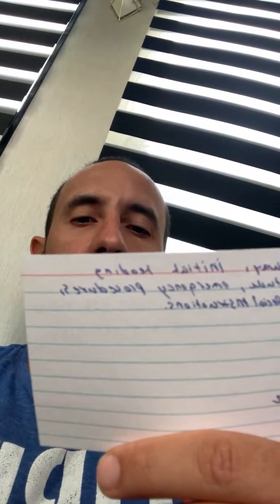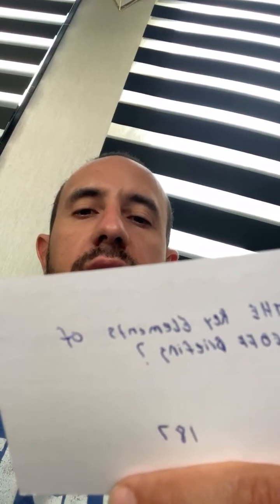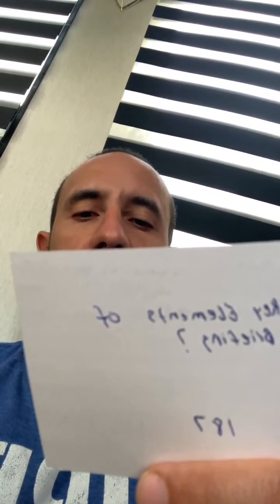What are the key elements of pre-takeoff briefings? Departure runway, initial heading, assigned altitude, emergency procedures, and any special instructions. Airman's Flying Handbook 2-22. I'll redo that one.